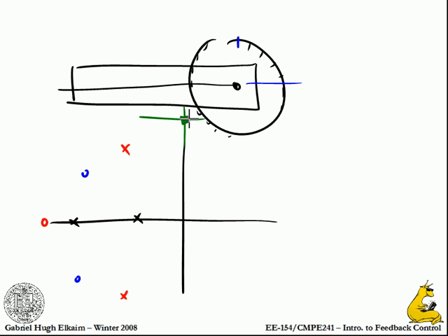So you would stick this thing up here, and you would hold the protractor part against the page, and you would move the bar until it lined up on the 0. Put your thumb on top of the little dot in the center, that little rivet. Spin the whole thing back up to horizontal again. Pin this back down. Go to the next 0. All right? That just added the phase of the 2 zeros.